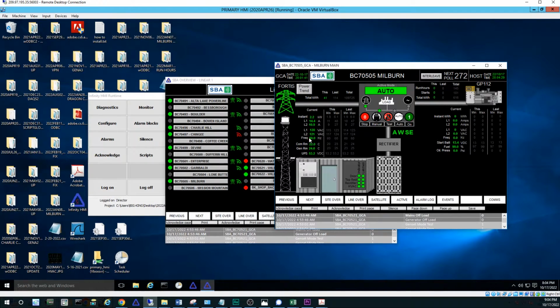At this site we have added a communications room temperature, generator room temperature, and UPS overall battery voltage to our analog metering. At this site we are also tracking some digital points, such as the door alarm, tower lighting top red light, rectifier failure alarm, and the HVAC circuit breaker. The indicator on the left is the current digital status, whereas the indicator on the right is the latched status.